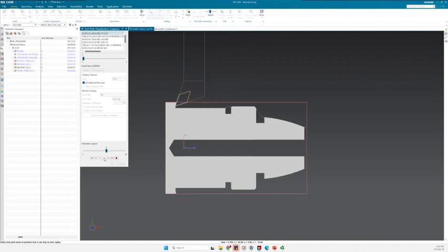So I have it clear now here. I can see now there are 2 problems existing. One of them is going toward this part, and this is the part that needs to be avoided, to not move all these, and these ones, and also this chamfer is not perfectly done. For this chamfer, most probably the correct approach is to define once the movement from here and then here. So I need to define maybe 2, 3 different operations. But for the sake of time, I will ignore solving this issue now. I will now try to solve this issue so that the tool doesn't come here.